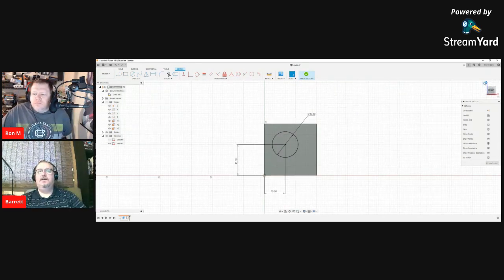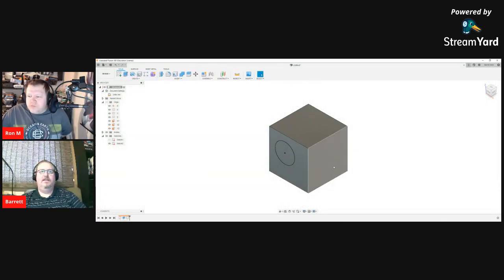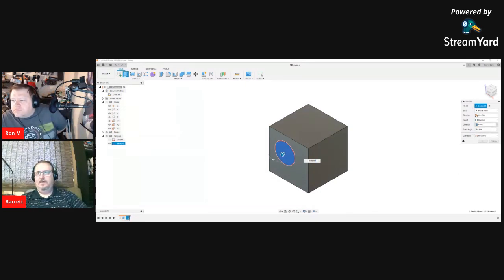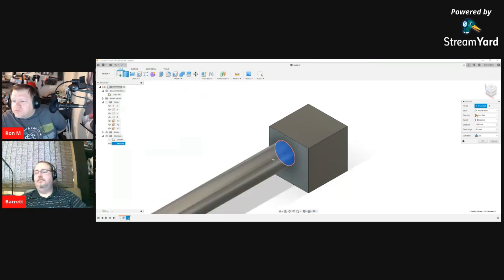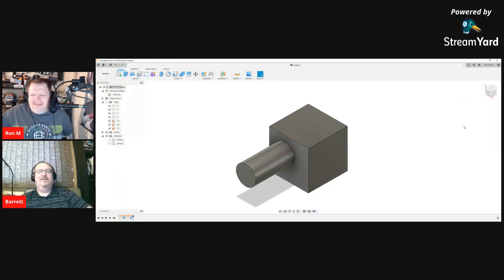Now while I'm still in the sketch view, or I can finish the sketch and I can extrude. I have two options here. I can make this a positive item, so 25. Well, that's a little bit large, not 2,500. So 25. So there is my peg.